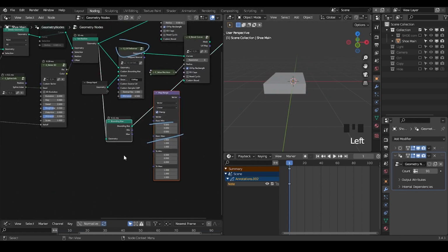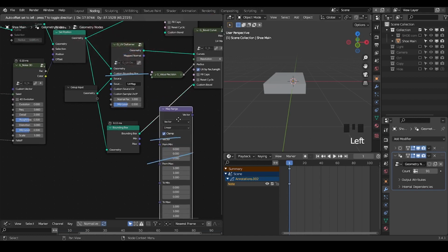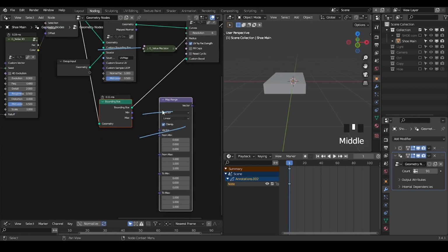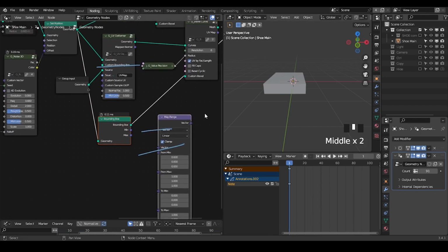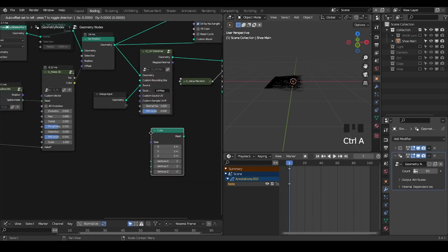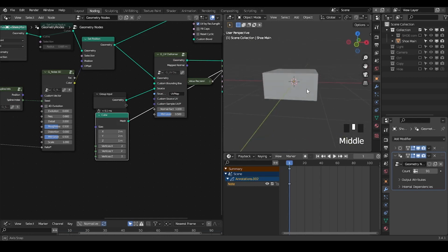So in order to solve that, we need a custom bounding box, and that's why there is a socket called custom bounding box in the preset. So that we need to make our bounding box to ensure that all this kind of map range or remapping process is stable instead of being going up and down, whatever. Okay. And to do that is very simple. We just create a kind of cube to cover the whole area. So this cube may be 2, 2. Something like that should be enough. You just need the height to cover the whole area of animation. Then everything should be done properly.